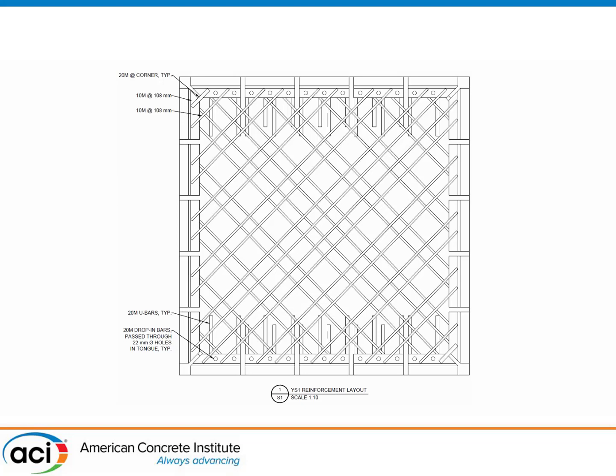Unlike normal specimens we've done in the shell tester, of course, this material has a significant post-cracking tensile strength, and as a result, the anchorage needs to be significantly more complex. I was nervous, frankly, that this reinforcement at the edge with all the additional bars would make a challenge for casting. I was wrong. The material flowed very well and had no trouble getting around the bars, and so our anchorage worked quite well. The way that tension gets into the specimen is that we have blocks with bolt holes in them so that the actuators apply to the bolt holes, go into the steel, and then get distributed into the concrete itself. The test region is sort of the central 2/3, and indeed that's where it failed as well.